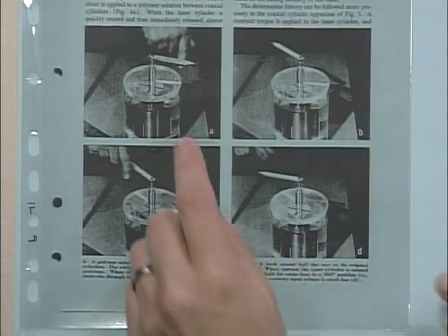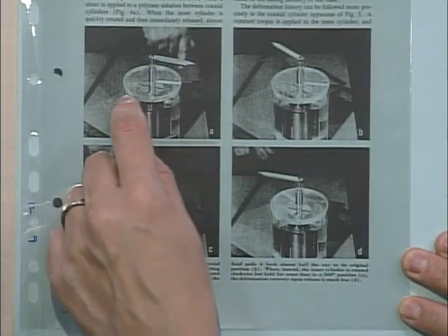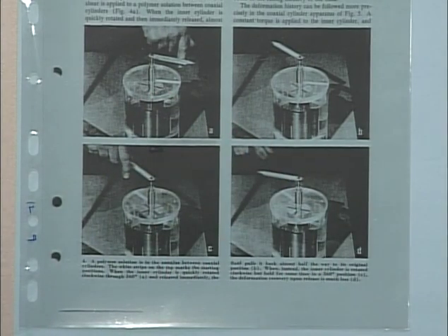Okay? If we said let go, these would look differently. They would go back also. We didn't say to go back. We said shear and stop. Make the shear rate go to 0. Don't let it be anything else. And therefore, there was a little bit of stress pulling back on it, telling it go backwards. That's what these guys did. He sheared it a little bit and it went back. And that's what the measurements say.